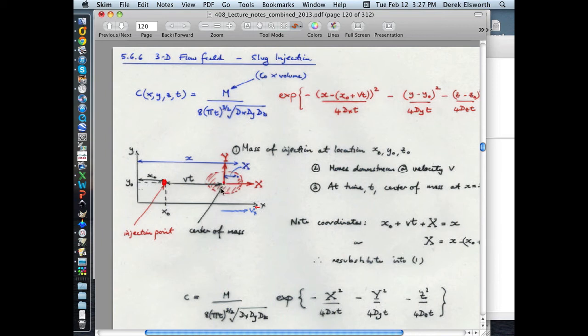And so the solutions for this are derived from these advection-dispersion equations also, but we'll just quote the results and say what the results represent. The results basically are a bell curve. If you draw a cross-section through this line here, this is a plan view, right? So this would be the outline of the plume as it's gone down gradient.